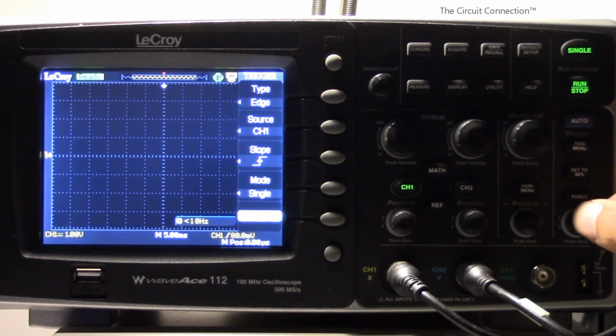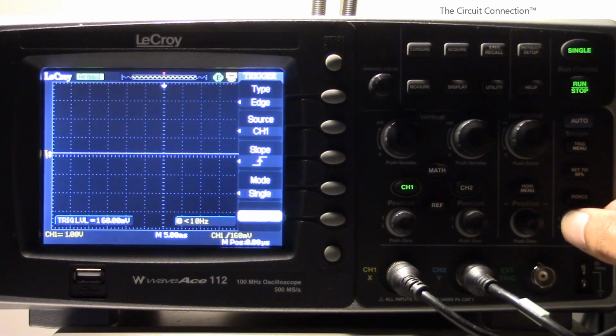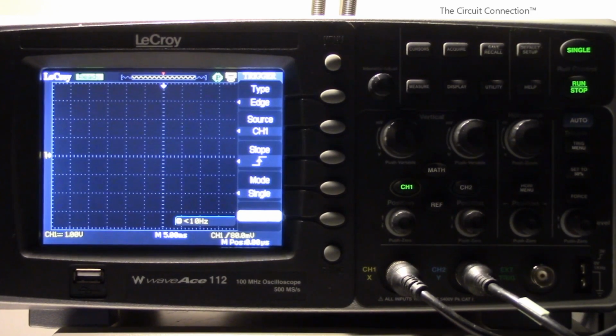Also remember that I want to make sure of my trigger level. See the trigger level there? By turning this knob, I can adjust the trigger level. I want to trigger it at about 80 millivolts. That seems to be about good as far as I see it. If it doesn't work, you can always try a higher setting, but you don't want it to be too high, because you want to capture it as soon as it starts to change. You don't want to set it too low either. It may not trigger, or it might be triggered simply by noise. So just set it to a normal amount, but don't overdo it in either direction.